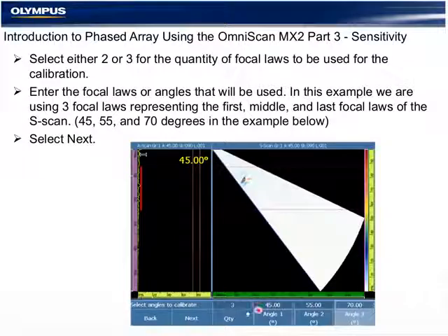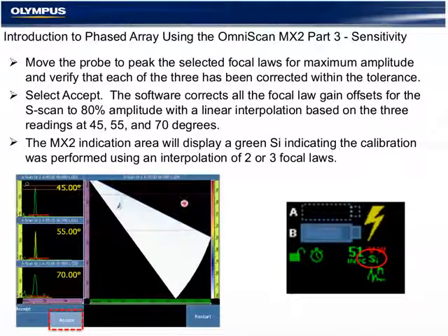One of the reasons we do this is because sometimes it's not possible to create a 75-degree sector scan because at the high angles, depending on the probe pitch and aperture, the beam mode converts and is no longer valid in the time of flight or calibratable because it's traveling under a different velocity. So when we can't complete the wizard for the 75-degree shear wave, but we want to include it because it's very useful for identifying and finding defects, we would enter a 75-degree sector scan, but only select the 70 as one of our 3 angles. This way, the software will fill in the rest of the predicted amplitude and not turn it solid red, which would impede our inspection.